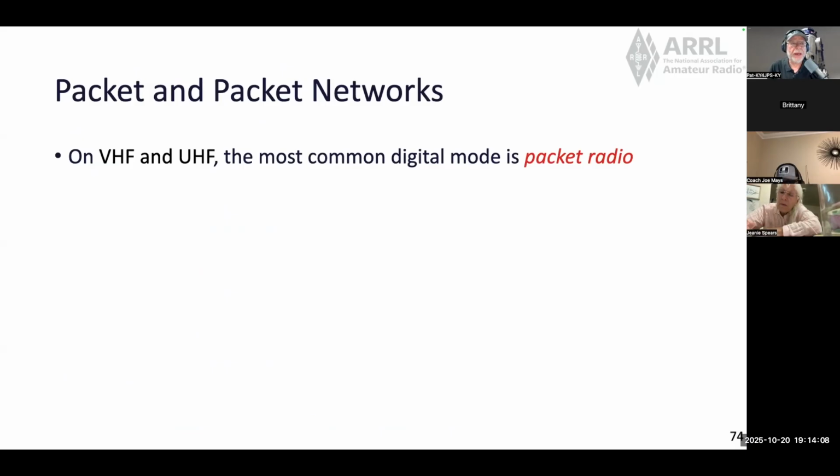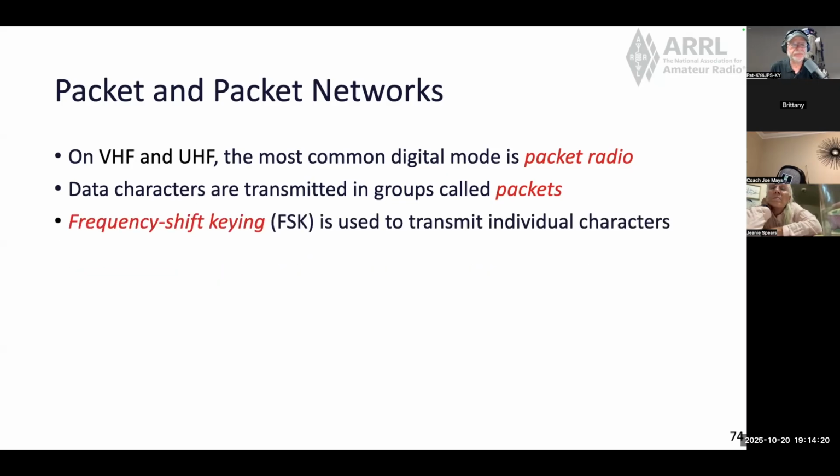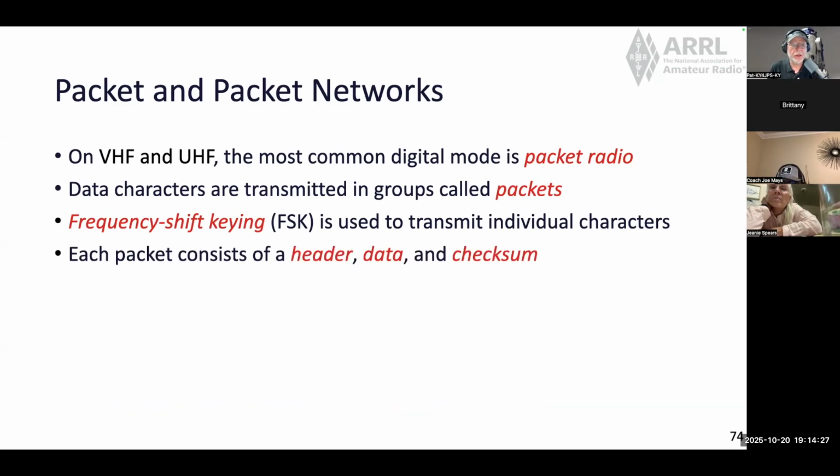All right. Packet and packet networks. On VHF and UHF, the most common digital mode is packet radio. Data characters are transmitted in groups called packets. Frequency shift keying is used to transmit individual characters. And each packet consists of a header, data, and checksum.